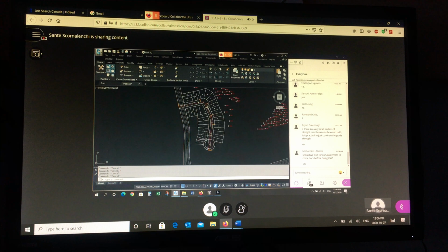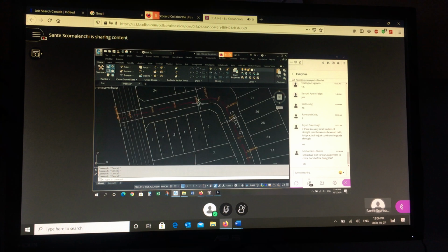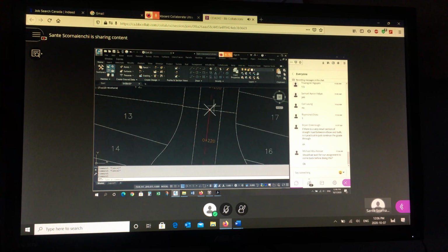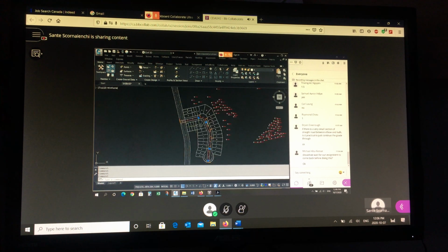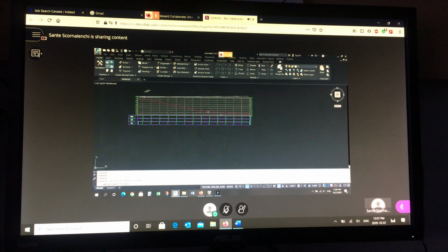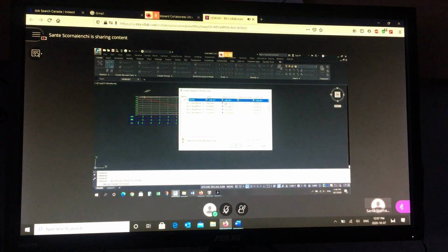Okay, so if I want to draw those points from the plan view to the profile, there's a handy tool for it. So if you click on it, right, 1, 2, I'm going to do all 4 at once. You can do one at a time. It's up to you. So if I know these points are in the plan, I want to identify them in the profile. I've selected them. You can see the blue dots, right? I go to my profile. So under Home tab, I go to my profile view, and there's a command called project points to profile view. So once they're selected, you start this function. And you go over to your profile and you touch the grid. And then it's going to give you this dialog box.